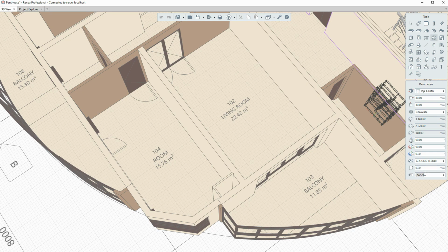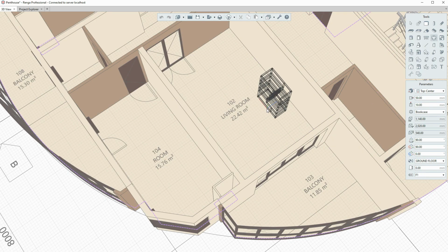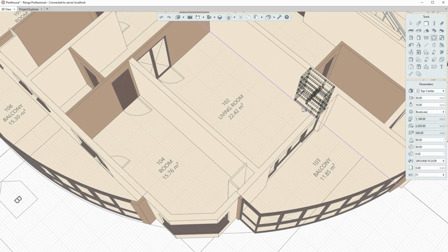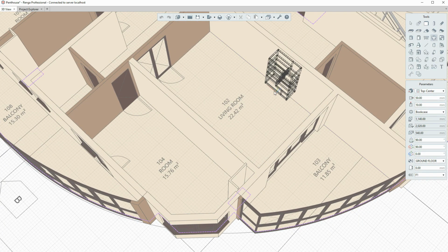Mark: it appears in the schedules necessary for insertion into the drawing. Then, specify the insertion point. All the above-mentioned parameters may be modified both in the process of object construction and when editing the element. Press Enter to fix the parameter values. All snaps and accurate construction are available when working with elements.